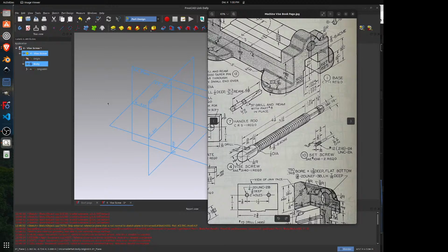And then you have to edit it in the individual features. Or you could have one sketch and have all these dimensions in the one sketch and edit them all within one feature. You have a sketch and a revolve. Again, that could be a matter of personal preference. But things like these relief grooves here are best done as revolves anyway.